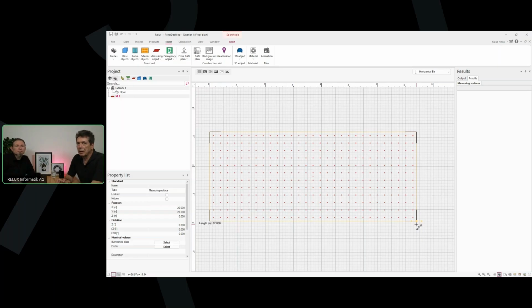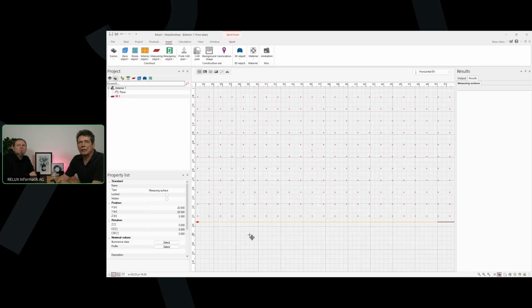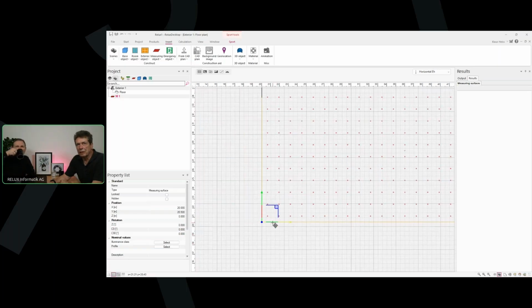It creates the grid points with more or less equal spacing in x and y. Not exactly equal, but more or less. The target is to create small squares, and it also takes care that each measuring point has the same small patch of surface for evaluating the average illuminance later and so on.